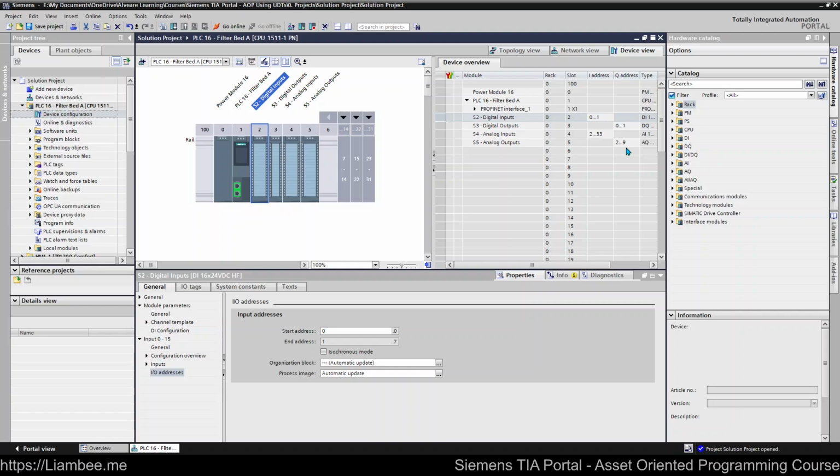And my reasoning for that is because when we go through the input mapping layer lesson, I decouple the I address and Q addresses from their respective areas in the program anyway. So we only ever use an I address once, and we only ever use a Q address once. And they're not ever used again, and it therefore does not matter what you're doing with them. Like in any project, they can change. That information can be obtained in a different way.